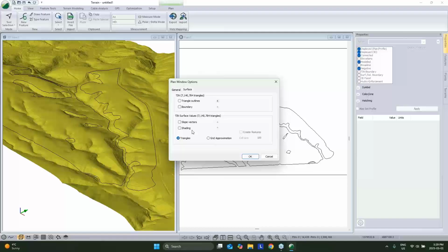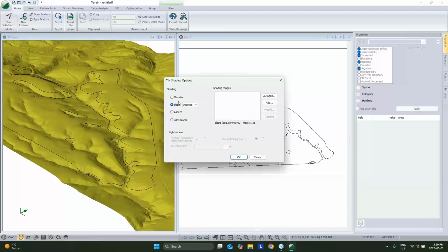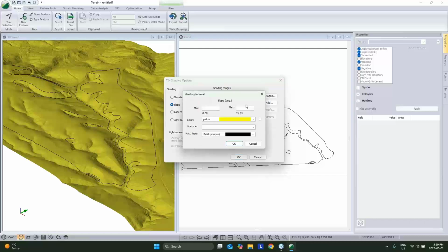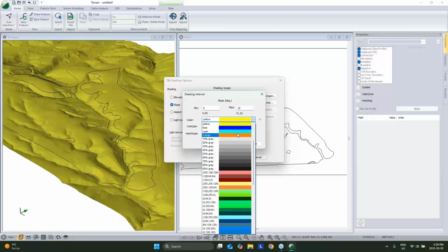We are going to come in here and, again, create some polygons. This time they're going to be based off slope. And of course, you can put in whatever values you'd like, but I'm going to say that if we have a slope between 0 and 10%, it's not going to be the topography that dictates where we are going.